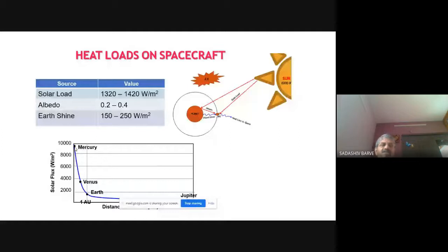Now, one more thing I will tell you: if the satellite goes away from the sun, say instead of Mercury, Venus, Earth, it goes to Mars, it is actually the other way around. Solar intensity, instead of getting close to 1.4 or 1.3 kilowatt, becomes half of that, close to 0.7 kilowatt per meter square. So the power generation reduces and the amount of energy